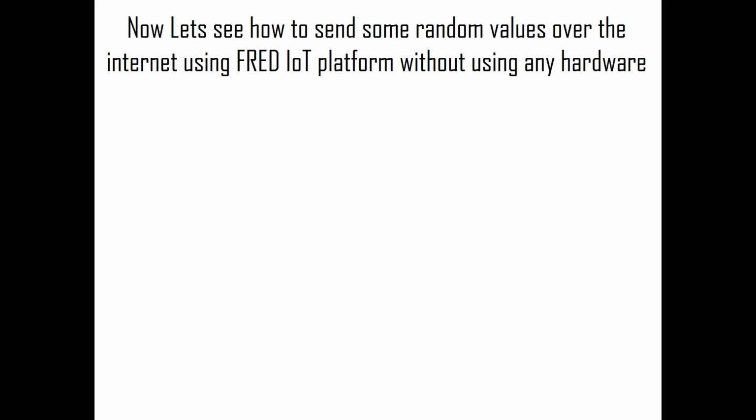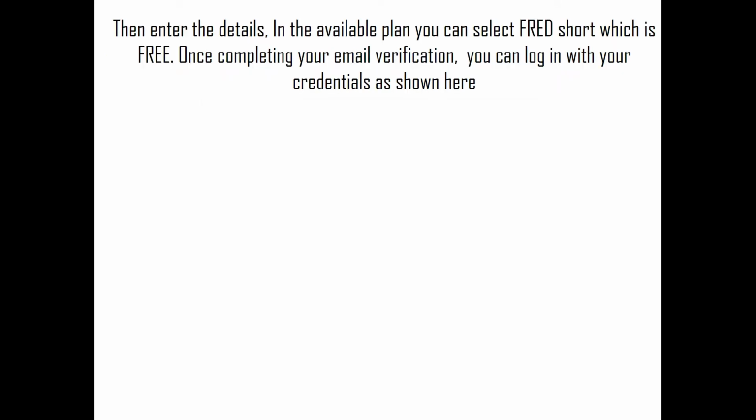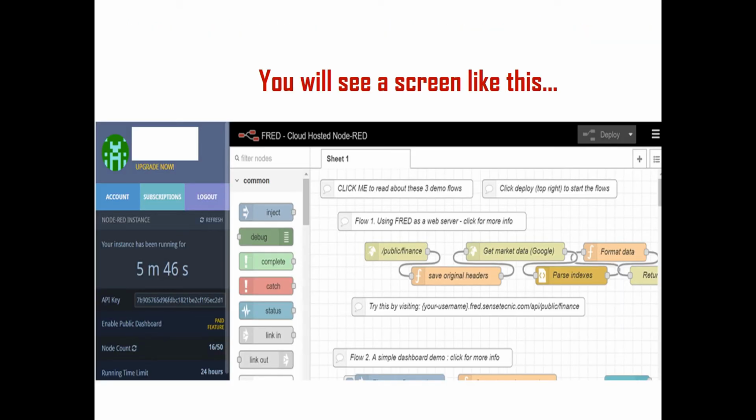So type FRED IoT in Google and go to the website called Sense Technic. And click the login button. For a new user, click the sign up button as shown here. Then enter the details. In the available plans, you can select FRED Short, which is free. Once you complete your email verification, you can log in with your credentials. Now you will see a screen as shown here, right? FRED is a front end for Node-RED, which is a visual tool for wiring IoT developed by IBM Emerging Technologies and the open source community.